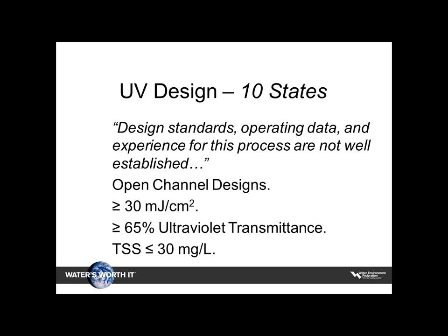And the other thing 10 States recommends is total suspended solids less than 30 milligrams per liter. It's actually quite high on that. Some may speak to turbidity, some don't. Those are the three big ones that 10 States always establishes. So if you're dealing with your agency, whoever's reviewing the facility from a regulatory standpoint, at least you know where the basis is.